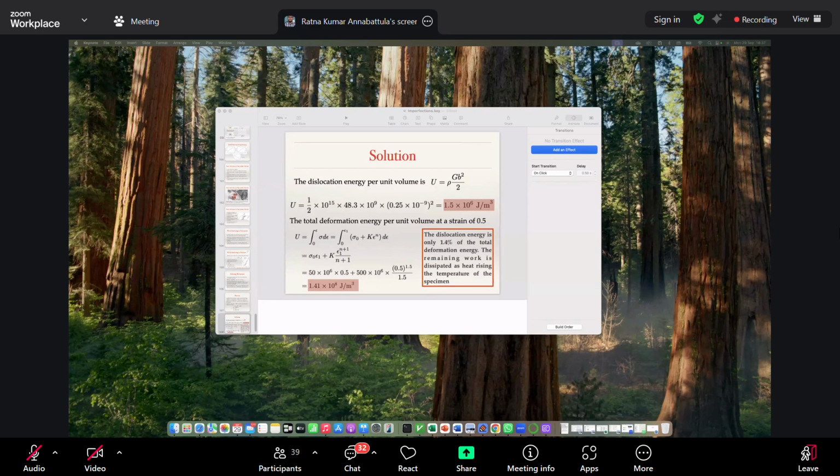The interaction of the dislocation with all these things is going to result in an increase in yield strength of the material, right? So that's how we discussed strengthening. In the process, we have also discussed a very important strengthening mechanism called grain boundary strengthening, through which we have introduced an interesting concept called strengthening of nanocrystalline materials.